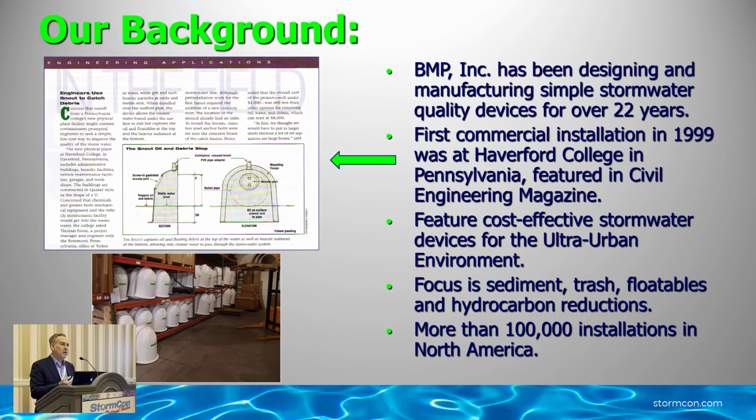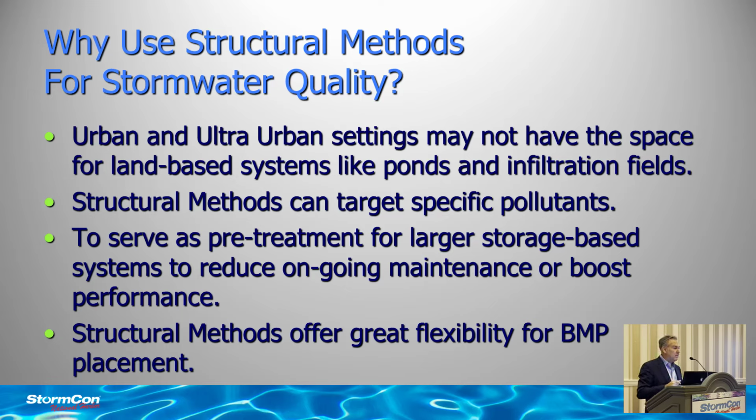Oftentimes these ultra-urban settings just don't have the space for land-based systems like ponds and infiltration fields. Or those ponds and infiltration fields need to be smaller, so we need to be more careful about what we put into them. The other thing about structural methods is you can tailor the tools you throw at your specific pollutants of concern. That is helpful to both the designer and eventually the site owner, because you're targeting specific pollutants with specific designs, and that helps.